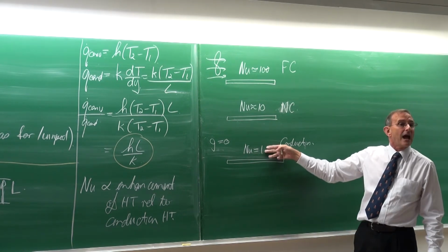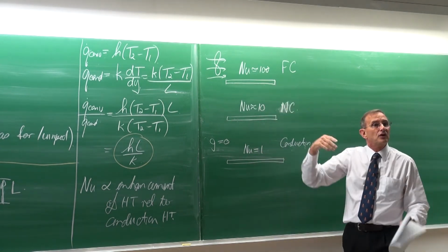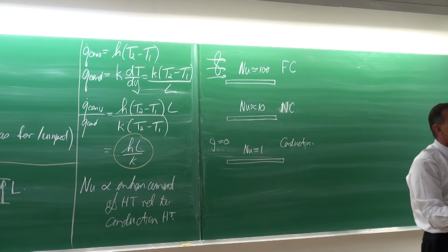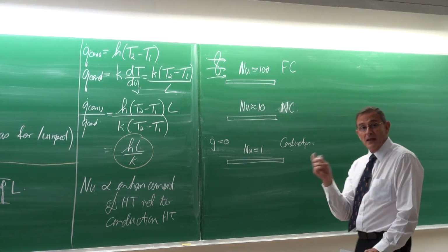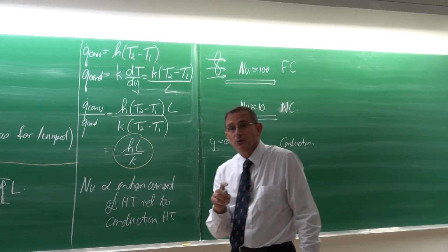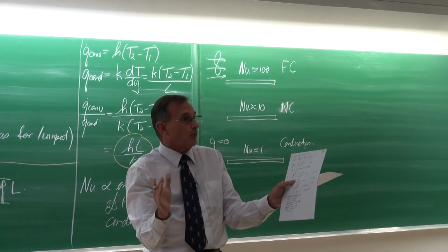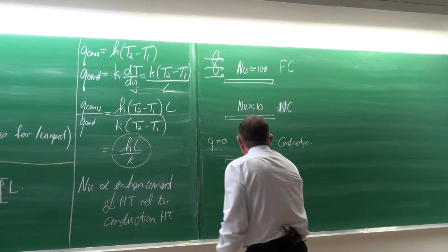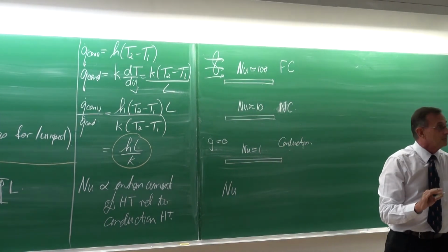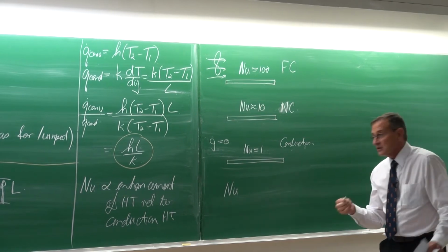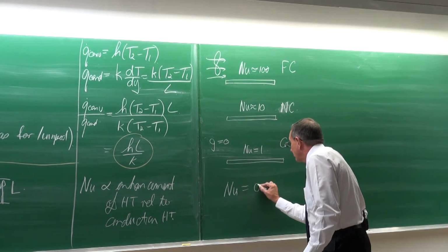The Nusselt number shows how the heat transfer has been improved or enhanced. That can happen very easily: you're going to have very fancy and complicated equations in which you have to calculate the Nusselt number, and all of us can make an error. You can end up with a situation where you calculate a Nusselt number of 0.8.